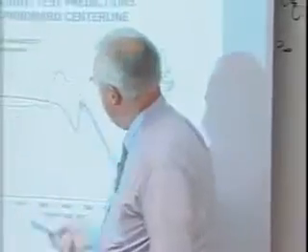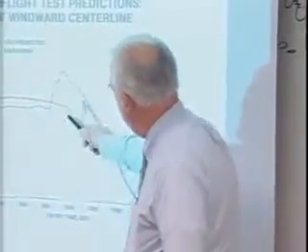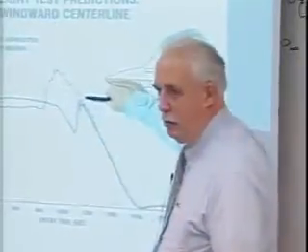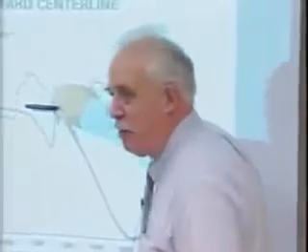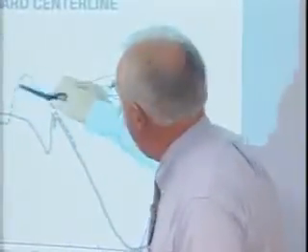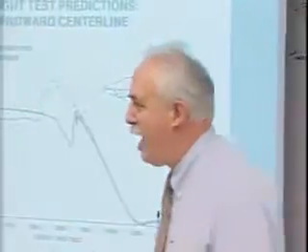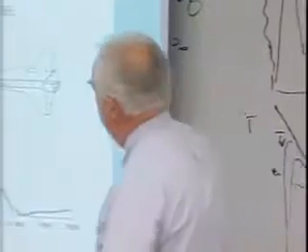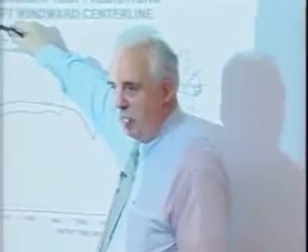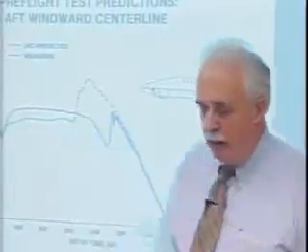And we're not doing as well. Certainly on transition, we knew we'd be very conservative. This is ideally how we designed the vehicle. Fly to temperature capability of the tile. And on this STS-3, right on. That's what we were trying to do. Now, if we exceeded this, that's all right, but we don't want to exceed the material capability, and we obviously don't want to exceed the structural capability.